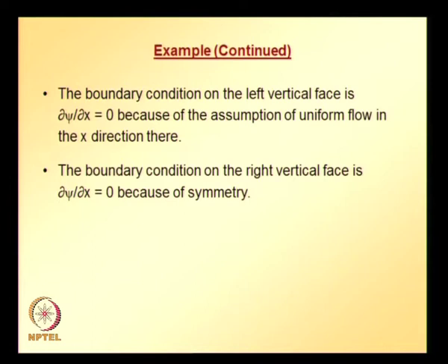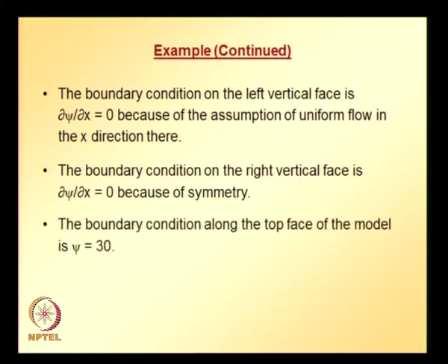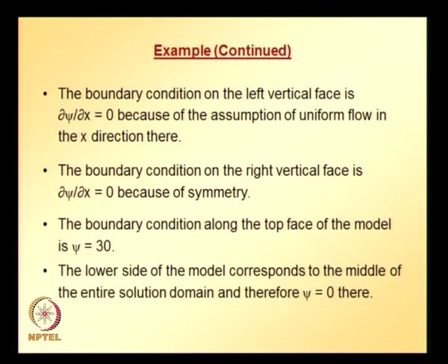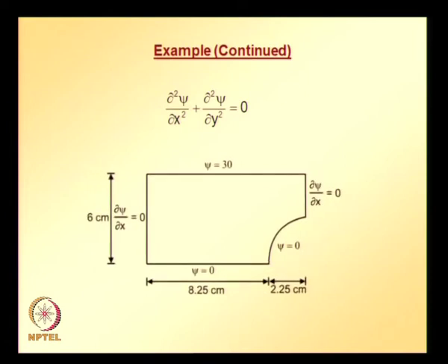The boundary condition on the right vertical face is the partial derivative of the stream function with respect to x equal to 0 because of symmetry, and along the top face of the model psi is equal to 30. The lower side of the model corresponds to the middle of the entire solution domain, so the stream function is equal to 0 there. So, that is the problem statement.